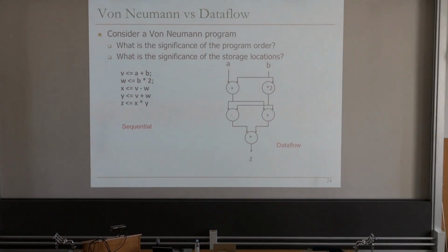And now you can map this nicely to a substrate that can enable you to flexibly instantiate each of these operations and the connections. And a reconfigurable logic, like an FPGA, is an example of that, right? You can map this nicely to an FPGA, assuming that each of the blocks enables you to do these connections nicely at this fine grain. So that's the beauty of the model. That's why data flow has been very important for programming FPGAs today.